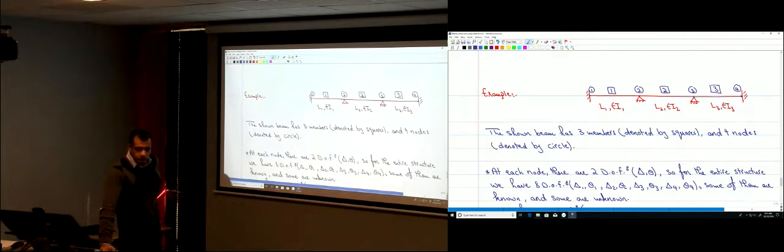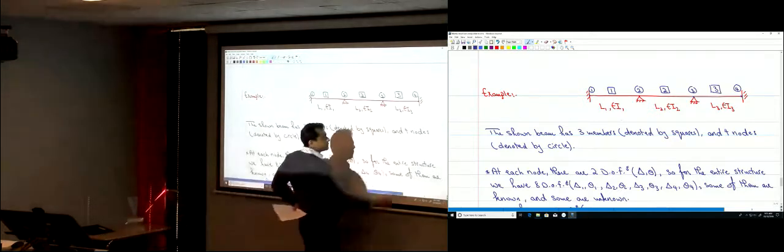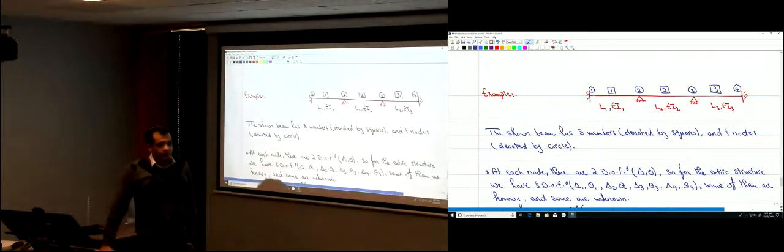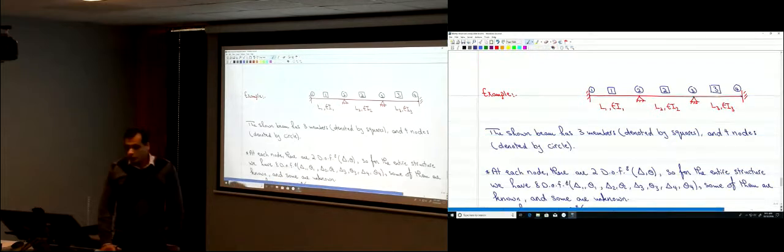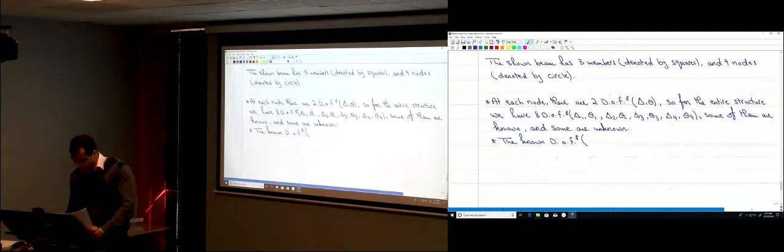Those are fixed supports. Those are pivot supports. Only up to those settlements. There is no settlement, so delta 1, delta 2, delta 3, delta 4 are zeros. They cannot move vertically, upwards or downwards, okay? So you have 8 degrees of freedom, but you know 6 of them: delta 1, theta 1, and delta 2, and delta 3, and delta 4, and theta 4. Those are zeros.